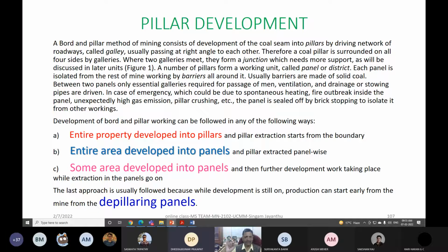That is the reason why, I hope in your previous semester in introduction to mining or mine development, you must have been told by your teacher, or learned through some papers or lectures or Google, whatever it is, that an elliptical shape of the shaft may be more safe or more stable compared to even the circular in a biaxial stress field, when the stress in one direction is more and in another direction is less.